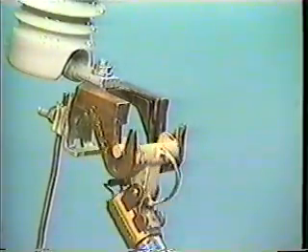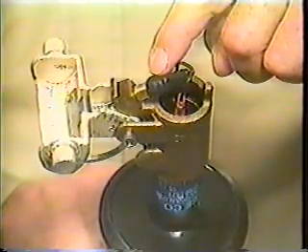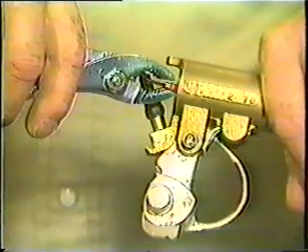When a sectionalizer operates, the probability is extremely high that a permanent fault exists. Always use your company's safe working practices for isolating and repairing the faulted circuit. After this is accomplished, remove the sectionalizer module so the actuator can be replaced. To remove the spent actuator, hold the sectionalizer module at the lower end, pull the insulated leads from the module tab, and unscrew the actuator from the lower end fitting.